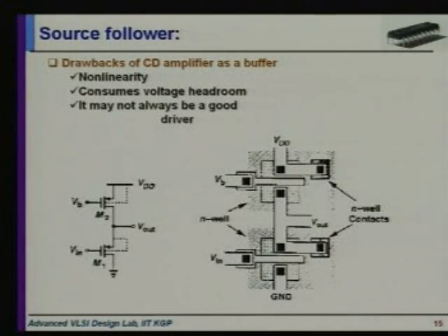The upper PMOS has the bulk connected to VDD, and for the lower case it is connected to the higher voltage among the three terminals, that is the source, drain and the gate. Whatever will be the higher voltage, the bulk will be connected to that particular node, and in that case the nonlinear dependencies of VTH on the VOV term can be more or less alleviated.